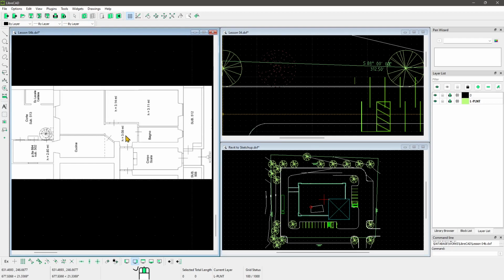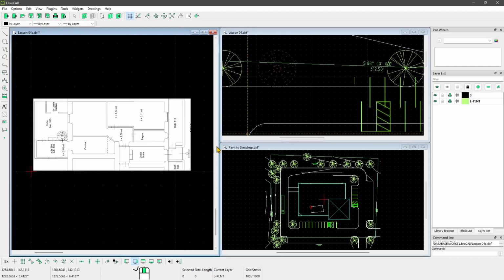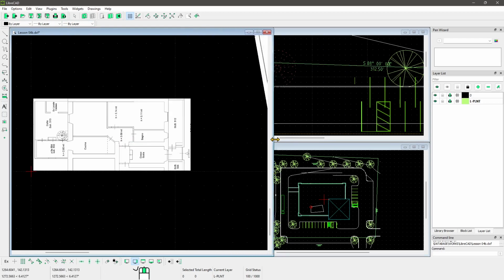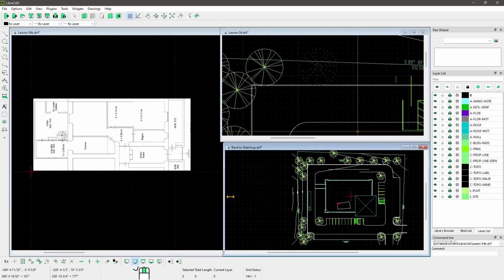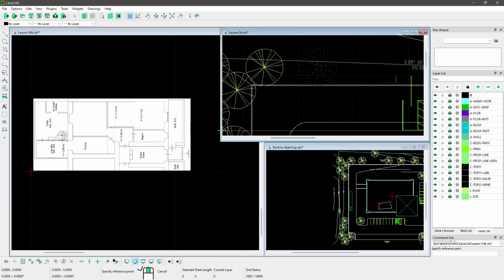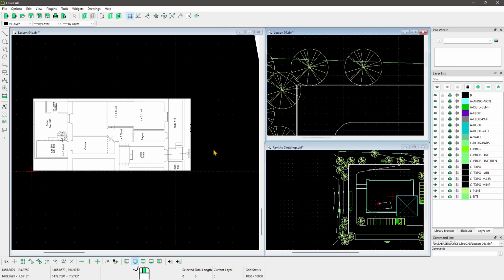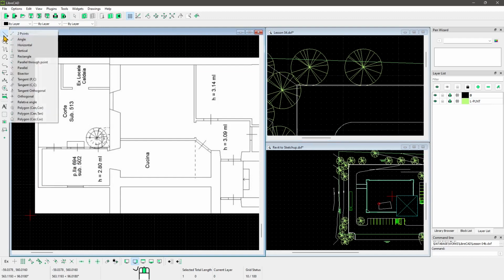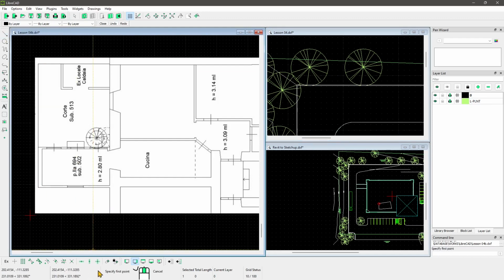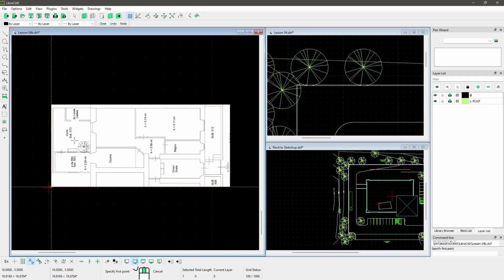Now, when we have a CAD drawing, we saw that things are better. So I'm just gonna expand this window just a little bit more. And I can also, of course, resize everything here anytime. Now here, I cannot use the snap. If I start to use the line and activate the endpoint snap, you can see that it only snaps to the corners, to the angles. So I cannot use it. So I need to turn that off.